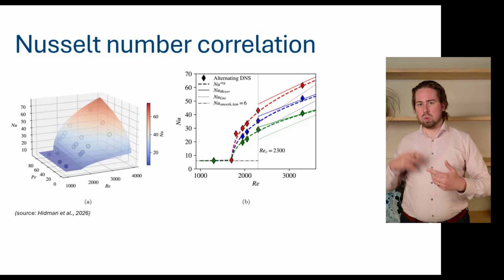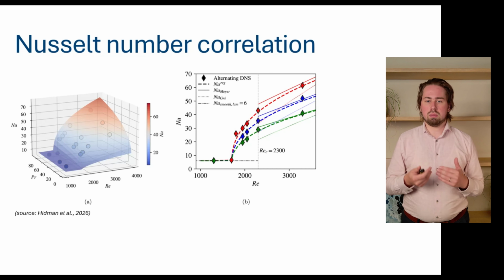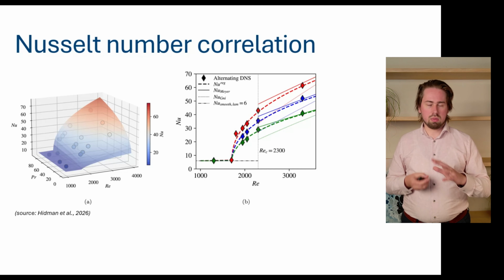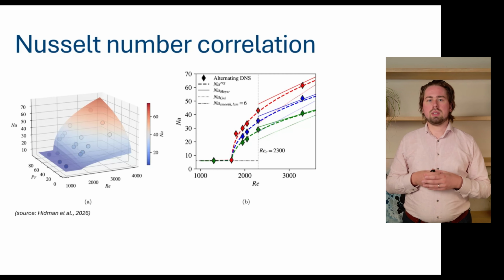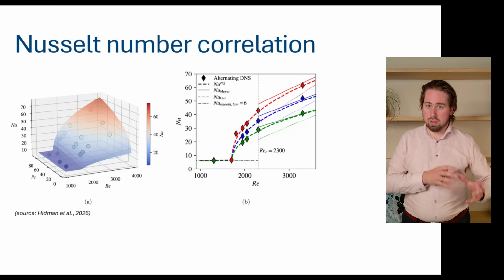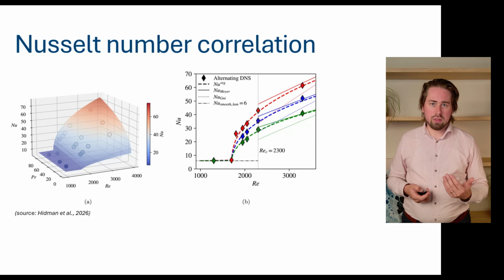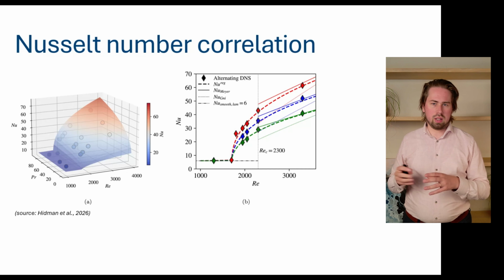Depending on which type of antifreeze you have, you will have a different Prandtl number. Here the green values are for a Prandtl number of 20. To put it in perspective, potassium carbonate is 25, and the red ones are for a Prandtl number of 75, which is around monopropylene glycol 33%.